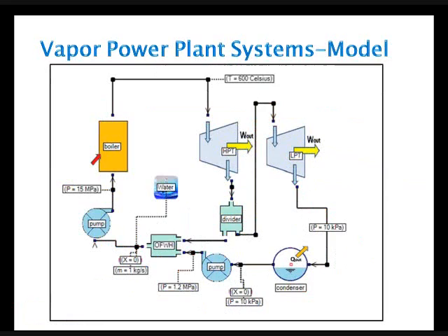So here, without going through ThermoFlo, you could just basically drag and drop all the components, and just as before, you put it here, and you set the mass flow rate as, again, 1 kilogram per second, because we're just looking at per kilogram analysis. We set the fluid to water, so we didn't have to do anything to change it. Set the pressures as before to the values, and that's about it.